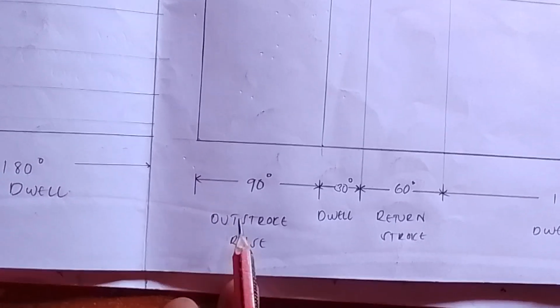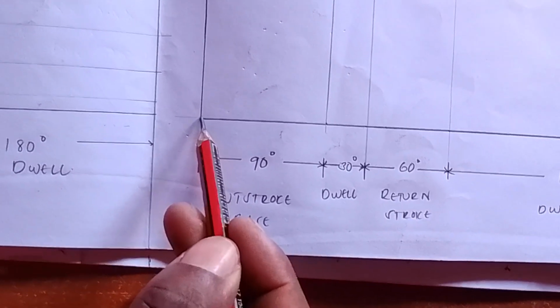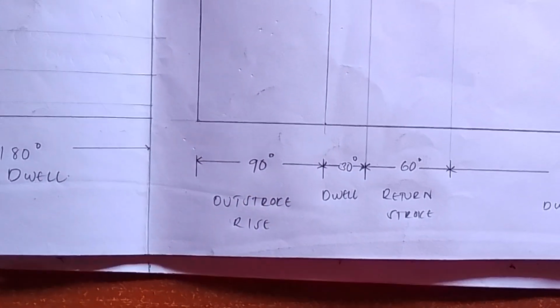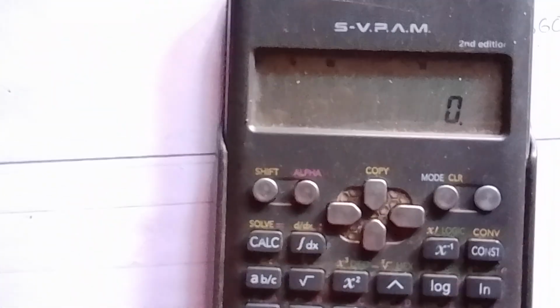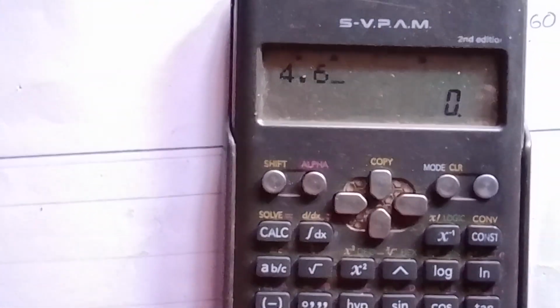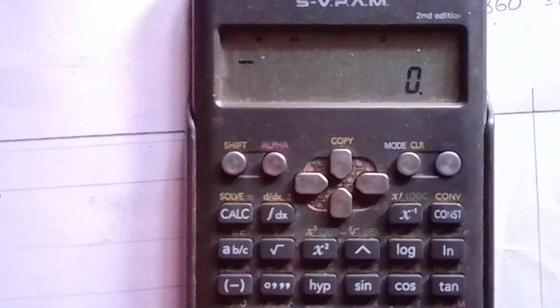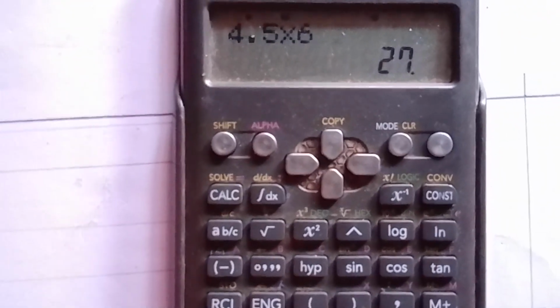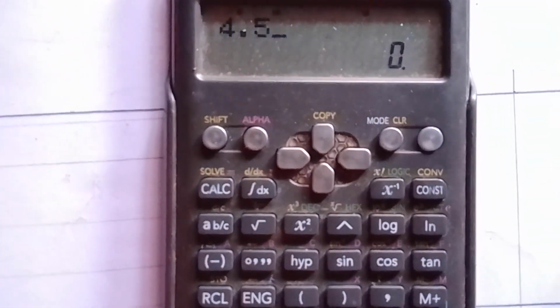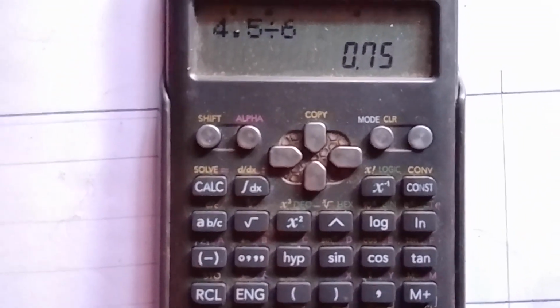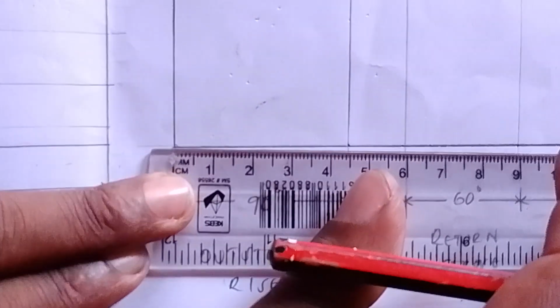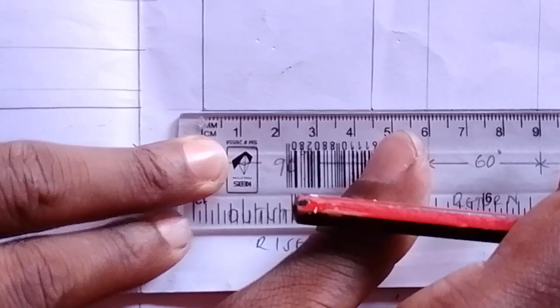This dwell, this outstroke, this 4.5 centimeter, from here to here, we divide it again into equal parts. I always say divide it into 6 equal parts. So you will say 4.5 divided by 6, it will be 0.75. So again, with your ruler standing at this particular point, you measure 0.75